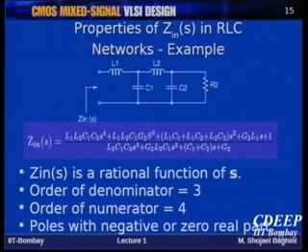If you make R2 infinite, then actually you will have all poles on the j omega axis. In that case, you will have an oscillatory system. So, you don't have any pole on the right side because these components are all passive components. Therefore, it is not possible to generate energy without any external source. If a system is unstable, it means that it is able to generate energy.